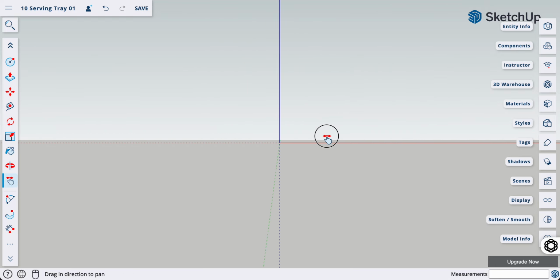And then I'm going to begin by drawing the serving tray handle. I'm going to start with the basic rectangle. Shortcut is R, or the icon is this rectangle tool here. I'm going to click once and then lift my finger and then gently slide my finger on my trackpad and type in my dimensions now. So the dimensions I'm going to work with are 280, 90. It will give me that rectangle piece, and there I will zoom into that area for me to work on. I will center it using the grab tool, shortcut is H, and move it to the center of my screen.